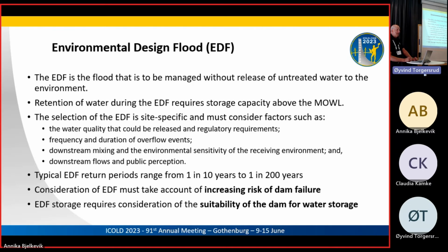And so they're not allowed to even have a spillway, which to me, and we had a bit of argument about this in our committee, but personally, I think that every dam should have a spillway, and all the dams that I've been involved with, we have a spillway of some sort. Even if there's one case where there isn't a fixed spillway, but there is a plan to develop one if there is an emergency situation, which personally I'm a bit dubious about, but at least that's better than having nothing.